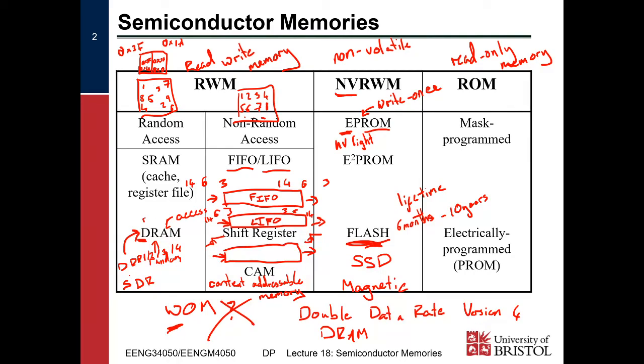If you look at DRAM on the other hand, you've literally got maybe 3 weeks max if you keep it only refreshing at the very lowest rate and you don't access it at all. But 3 weeks is quite a generous estimate. Maybe a month, right? So it's all a matter of scale, and like flash, at the end of the day, when you turn your device off, your processor powers down, and it powers down your DRAM anyway. Flash, obviously it doesn't power it down.